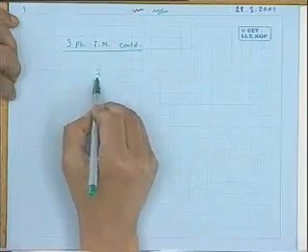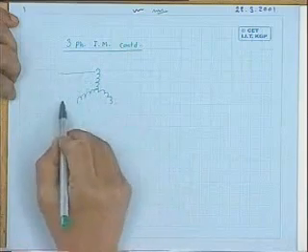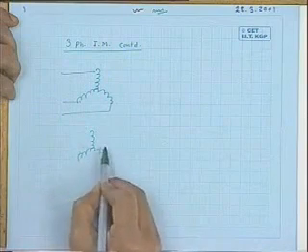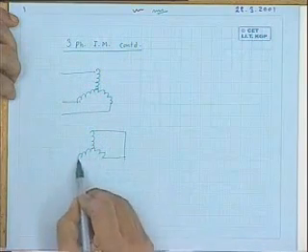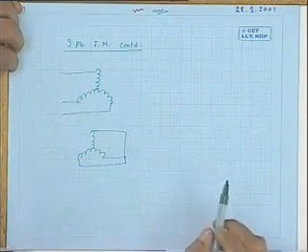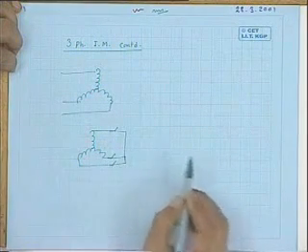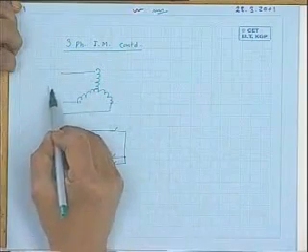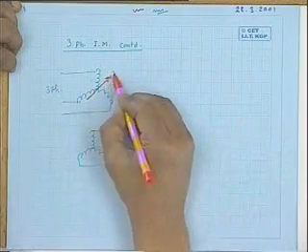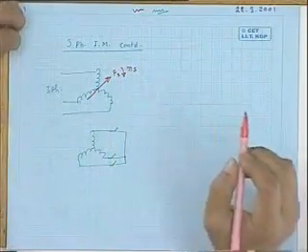See, the idea is that a three-phase induction motor has a balanced three-phase stator winding and a rotor winding, and the rotor winding will usually be kept shorted so that it can produce torque, the rotor can carry current, etc. Now, what I am trying to tell, imagine first that the rotor terminals are open. Now, if you apply three-phase supply, a rotating field will result, Fs, the stator field, and it will start rotating with speed ns.